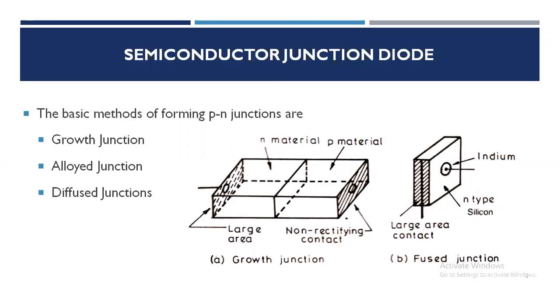The type of junction we seek is a change from n-type to p-type material in a single crystal. Therefore, we may change the dopant from donor to acceptor during the growth of the crystal. Alternatively, we may introduce impurities of one type into regions of a crystal which was grown with lighter doping of the opposite type. In either case, only the doping is changed at the junction. There are no gross changes in the lattice structure itself.